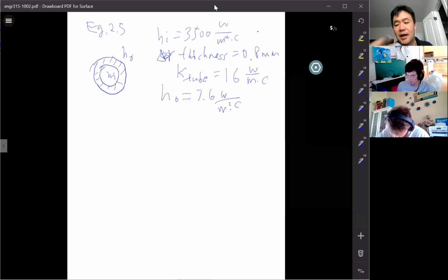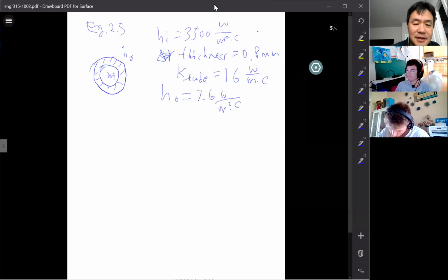Okay, heat loss. Well, we can do the heat loss first. Okay, we can even try the thermal resistance. Then we find out what is the overall heat transfer coefficient. Overall heat transfer coefficient is U, right? Okay. So you have 3 items here, obviously. Right? This is inside the convection. K, outside the convection.